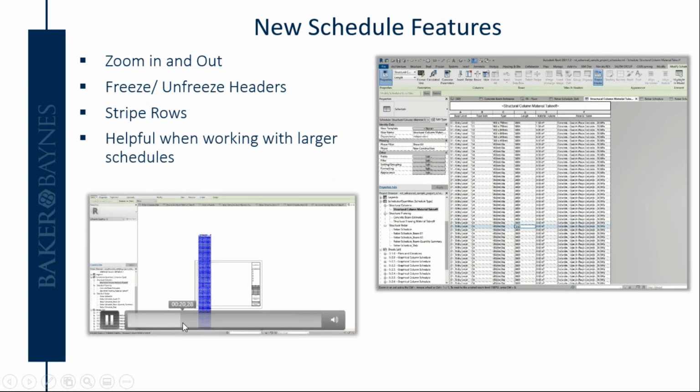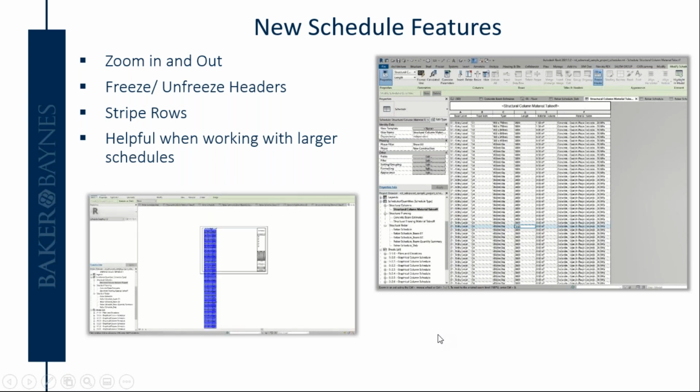So what you can do is split the schedule and then have the various segments placed on the sheet next to each other. And then there's a little blue dot at the bottom that you can drag. As you are reducing the one column, that information is being spilled over to the other side. And then again, you can just keep on splitting and adjusting until it suits the size of your page.